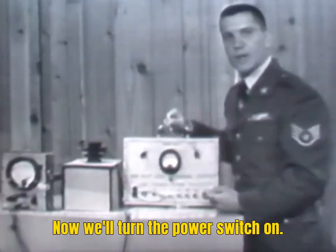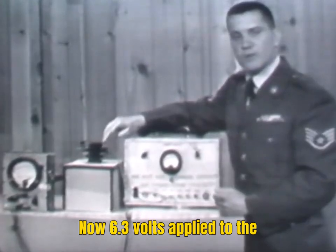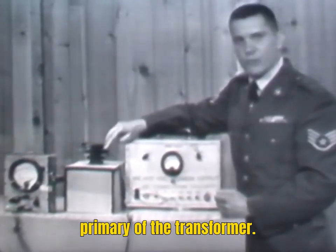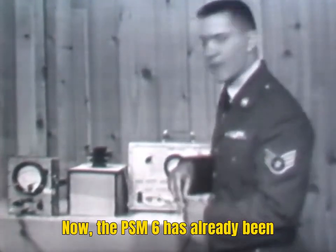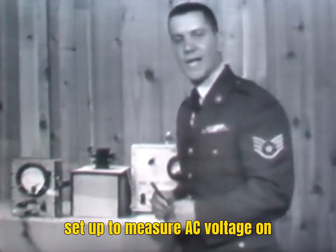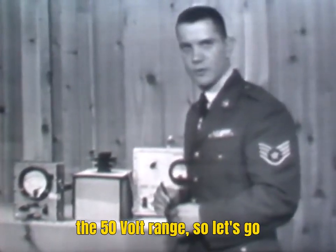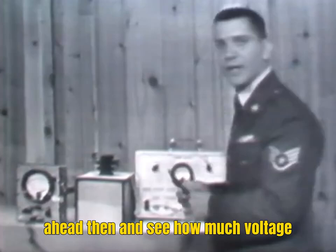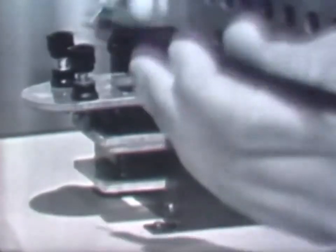Now, if we turn the power switch on, we have 6.3 volts applied to the primary of the transformer. The PSM6 has already been set up to measure AC voltage on the 50-volt range. So, let's go ahead and see how much voltage is available at the secondary.